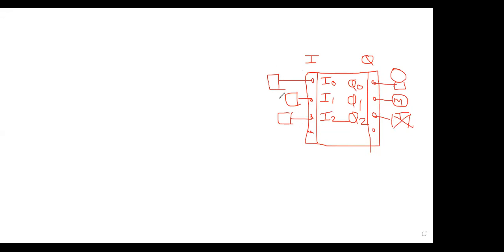But just by connecting inputs and outputs to the PLC, it's not like you will press the first switch and your first output will be on. It is not like that. After connection, you need to send some program. If you don't have a program inside the PLC, your machine won't run. So you press the switches, nothing will happen. So you need to send a program.